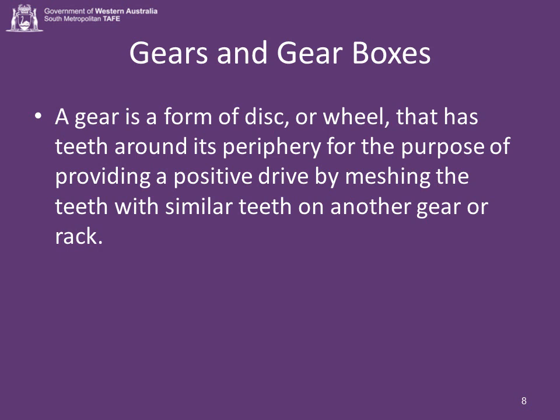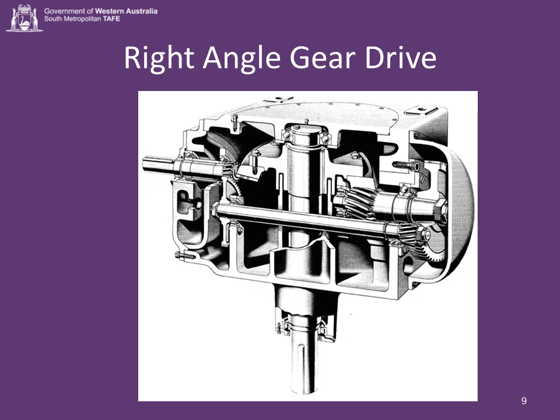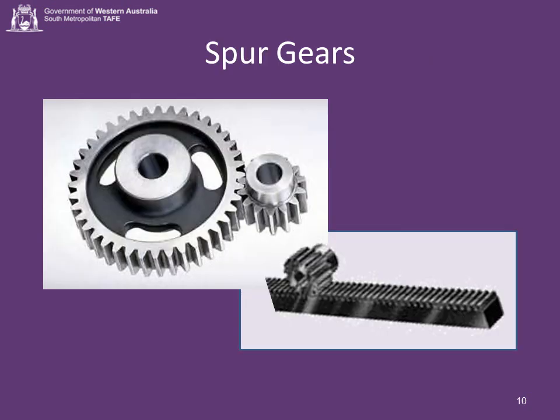So a gear is basically a wheel with slots cut in it. Here's an example of a fork type direct torque DTC right angle conveyor drive. It has helical and spiral bevel gears. We'll be looking at those later. Spur gear might be called the basic gear, since all the other types have been developed from it. Its teeth are straight and parallel to the center bore line, as shown above.